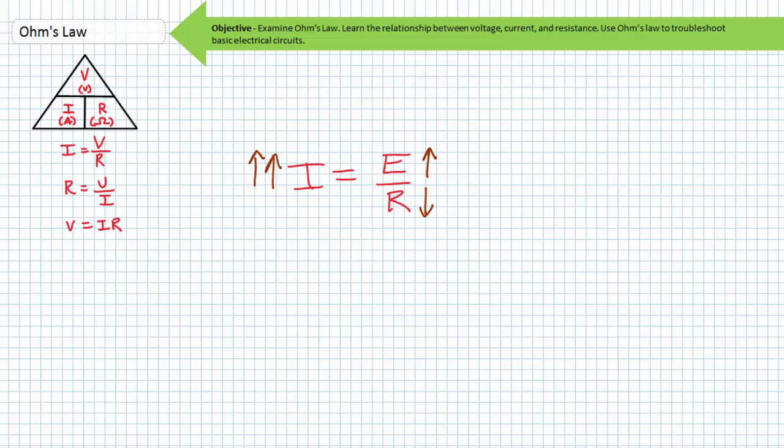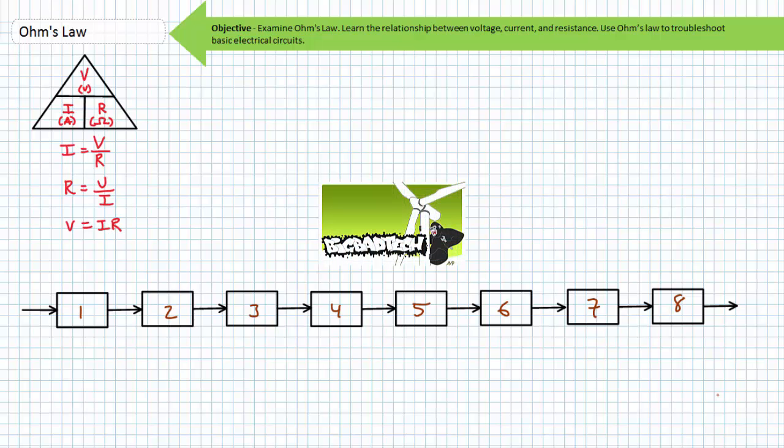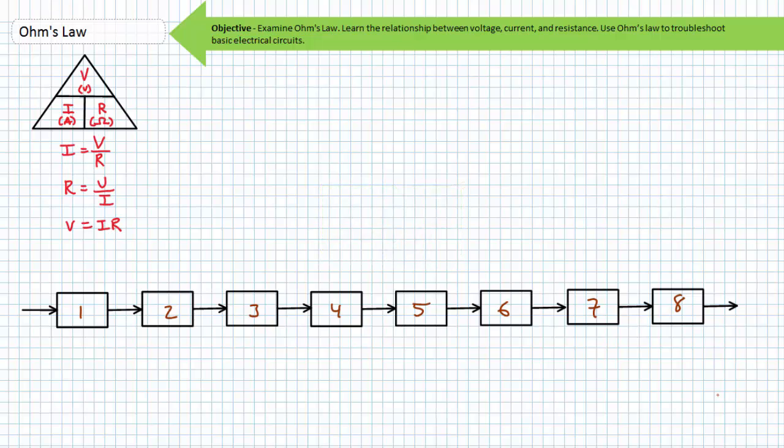Regarding the efficient and timely identification of problems within a system, realize the undesirable symptoms might have many possible causes, and quick diagnosis of the issue and subsequent correction is what identifies a technician as a good troubleshooter. In short, good troubleshooting is the combination of solid technical understanding of properties like Ohm's Law with good, organized, and efficient work practices. Recall from the efficiency lecture, available at the Big Bad Tech channel, where I introduced the concept of linked subsystems forming a larger system.